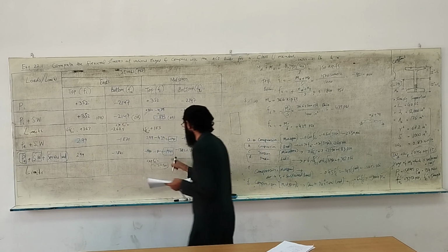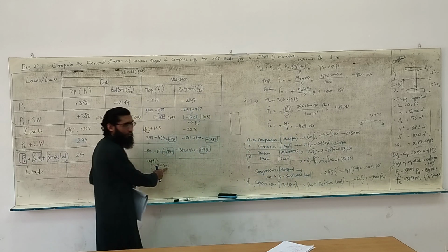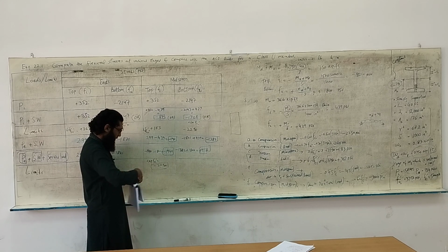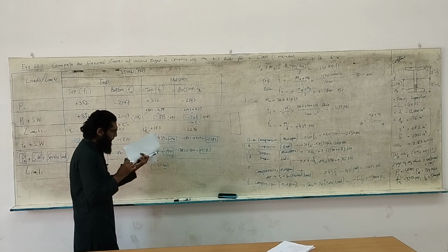So this is the limit. Now just quickly compare this. We will allow 2250 psi of compressive stress at this stage, and we are having lesser than that, okay. So this is fine. And what about the tension?